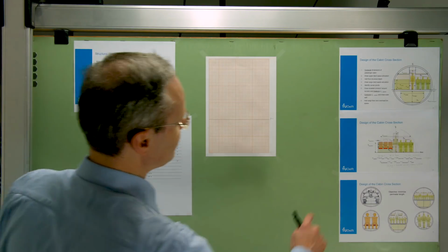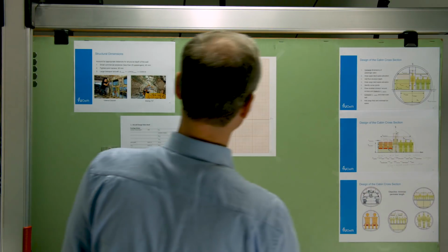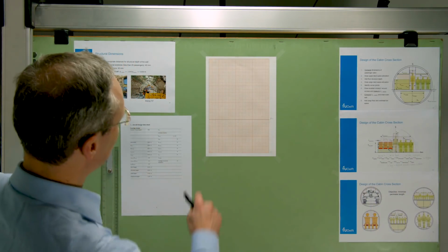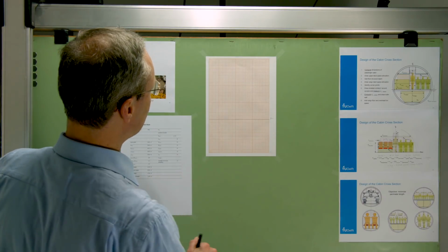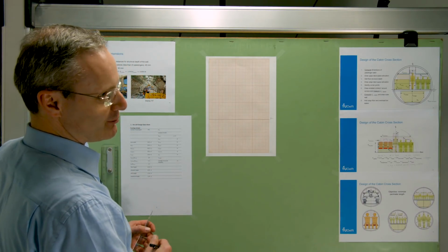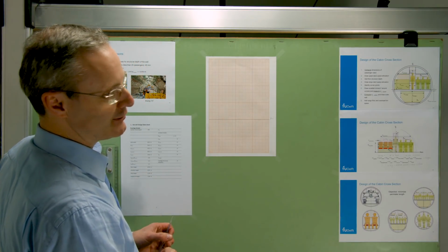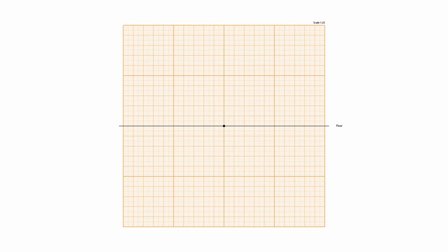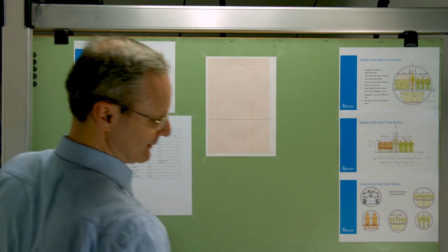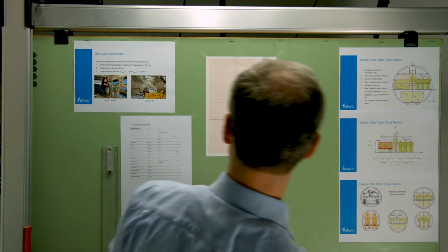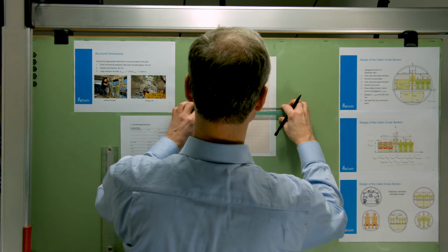So that line, this line that I'm going to draw here, is going to be 38 millimeters above the floor line. The nice part of this graph paper is that this is indicated in millimeters. So 3.8 centimeters is a little bit less than 4 centimeters. And these blocks are 1 centimeter large, 10 millimeters by 10 millimeters. So I can use this one.